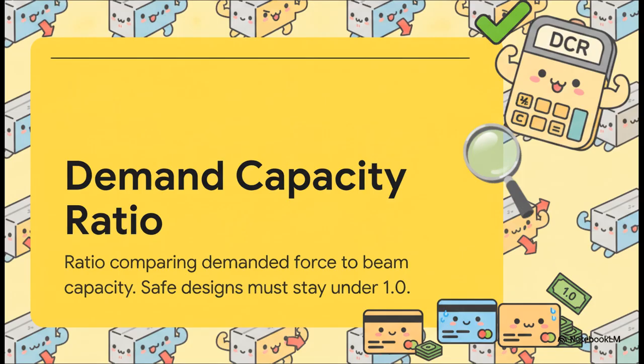And this brings us to arguably the most important metric in structural design, the demand capacity ratio, or DCR. It's a very simple question. Are we demanding more from the beam than it has the capacity to handle? Think of it exactly like a budget. If your DCR hits 1.0, you are totally maxing out your credit card. A truly safe, compliant design absolutely must stay under a DCR of 1.0.